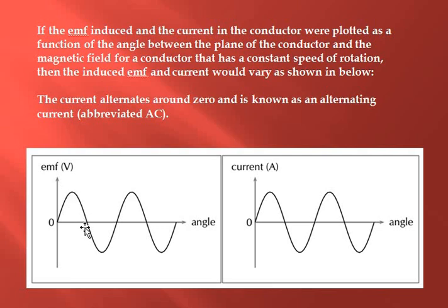Then it descends as the coil continues to rotate and loses contact with some of the field lines, until it gets to 0 again, and then goes deeper down and reaches the maximum. This maximum here is when the coil is on the other side, when the side of the coil is down. Then it goes up again until it gets to 0. So it's actually a sinusoidal wave, and it is a repeating cycle.